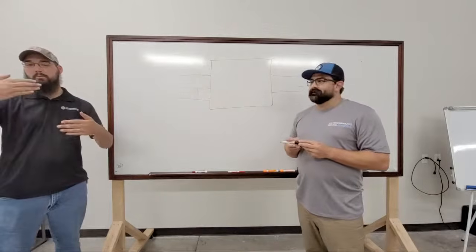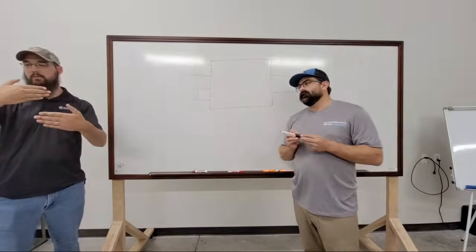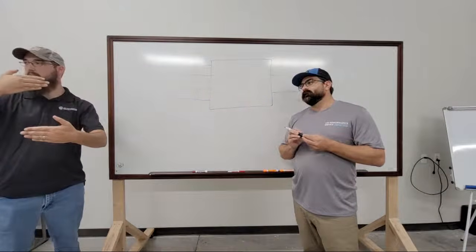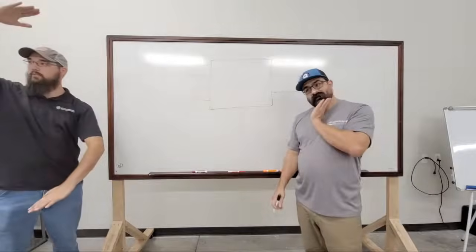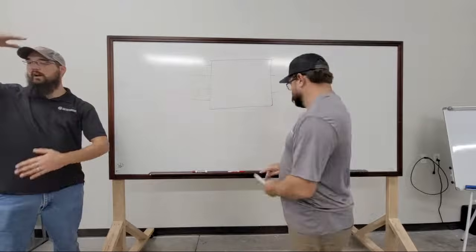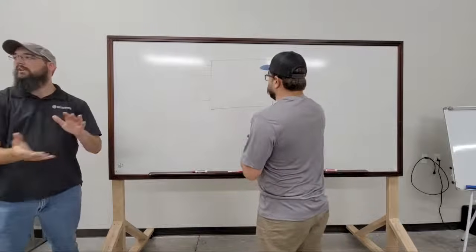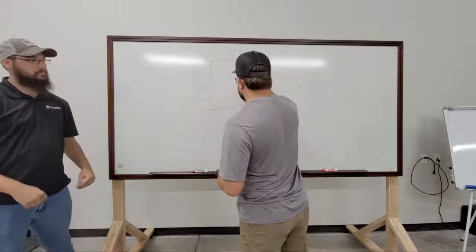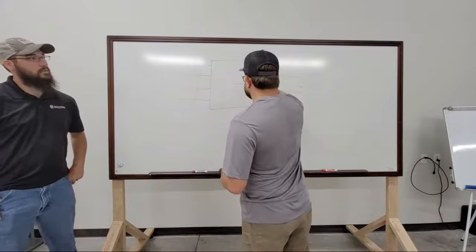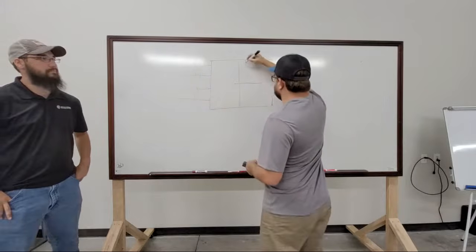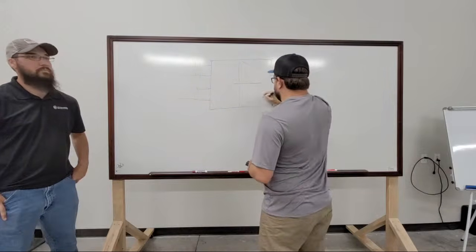With a hot deck and cold deck, the coils will literally be split in half. So instead of being a full length or full height coil, the bottom half of the coil will usually be the cold deck. You'll have an air handler and there'll be a split, and it's kind of a layer on top of each other.